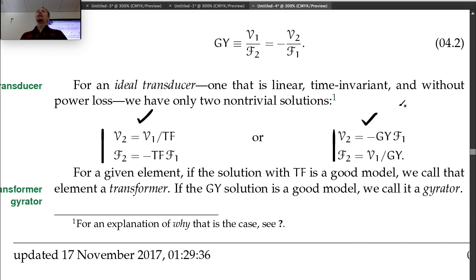If we include fluid systems, there's a really good example. The piston cylinder goes from a pressure, which is an across variable for a fluid system, to a force, which is a through variable for a translational mechanical system. So you have a gyrator. So the piston cylinder is a gyrator. I couldn't think of one for an electromechanical system, unfortunately. Maybe one day, maybe one of you will invent something like that, and then I'll be able to use it as an example in class.